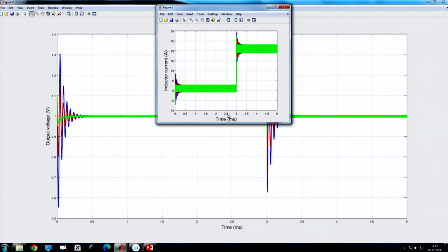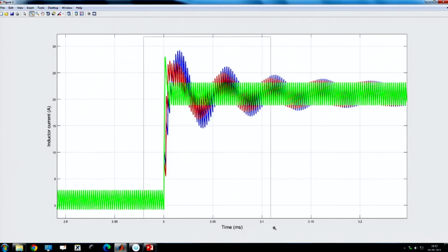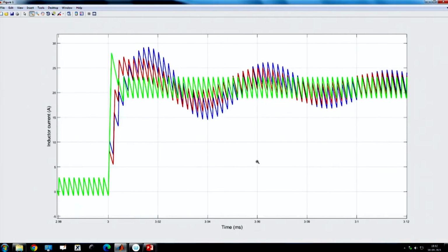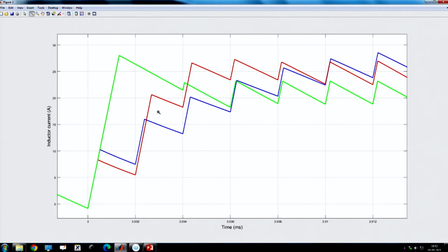And if you go to the inductor current, you see the inductor current is not very significantly high, but our traditional approach of designing has this, because of the model validity and small duty ratio. You will see the difference in the fast recovery time, since the small signal approach requires low duty ratio perturbation. During the slew up process, there is turn on and off happening, and because of that it slows down the transient response, whereas the large signal tuning allowed duty ratio saturation.